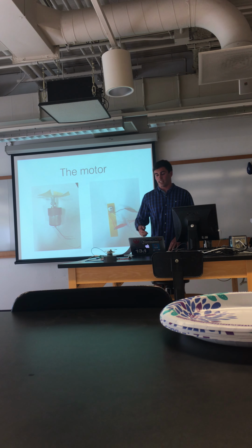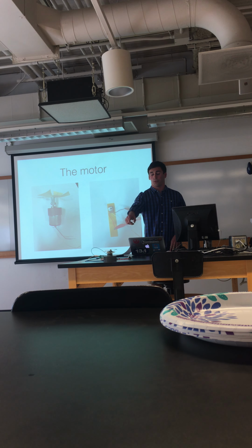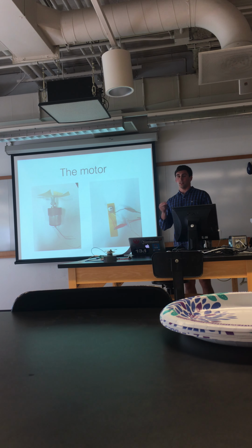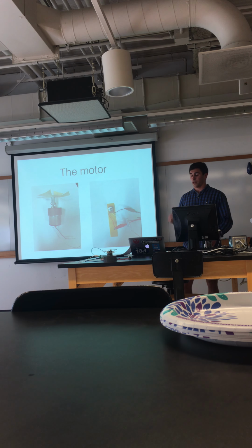This is just a very simple knob. What it does is it takes power from the battery, that voltage runs through the knob, and then the knob controls how much voltage I send to the motor. The reason I had to do that was because it's a DC motor, so the speed that it turns is directly related to the voltage running through it.